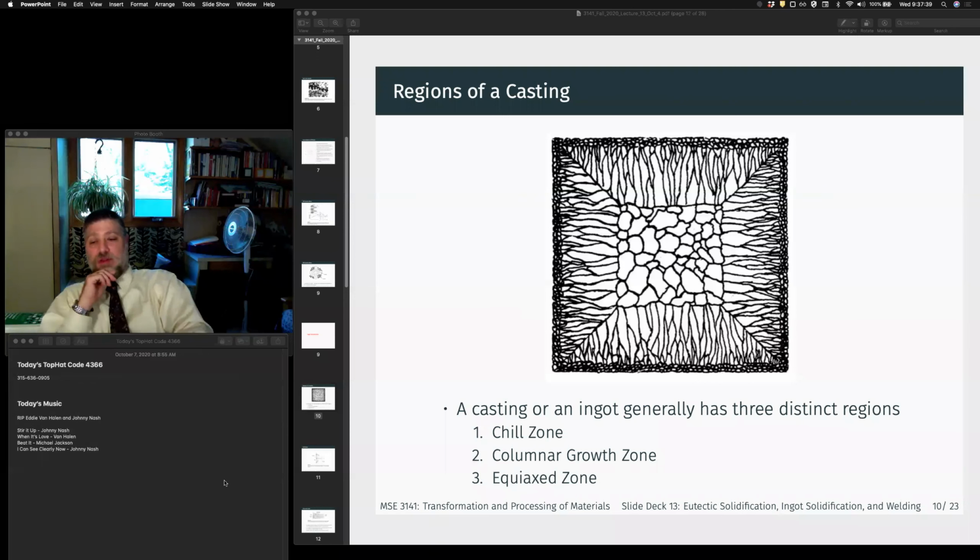So the turbine blades, Ethan, are grown as single crystals, right? In terms of ingot casting, these grains can be really huge, many centimeters long, right? So typically, if you have a casting like this, you would then need to do a large forging or some other processing, rolling, reduction, right? Typically, you don't use a cast microstructure in this state, right? So we'll talk about thermomechanical processing at the end of the semester.